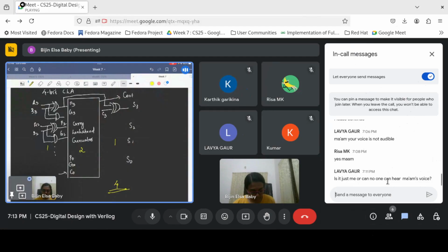Is this clear? Here it's 1 nanosecond. Here it's a 2 level logic design, so it will be 2 nanoseconds. Then here you have a XOR gate, so that will be 1 nanosecond. So constant time is the propagation delay for the carry operator for the bit.